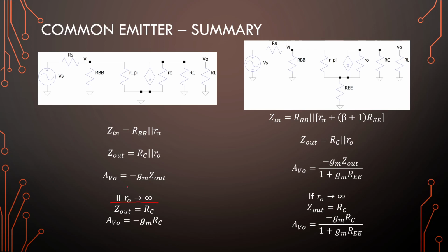You can work with this included. It will just appear in your output impedance in general, and later with the simulations you will see that the gain is a little bit off, but not by much, and that is because we decided to neglect the effect of R out of our transistor.